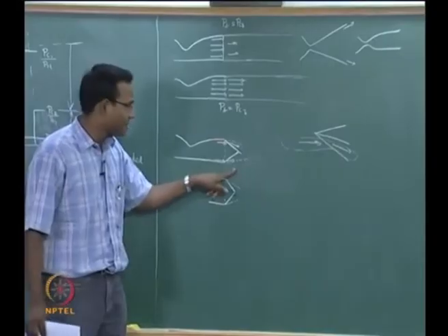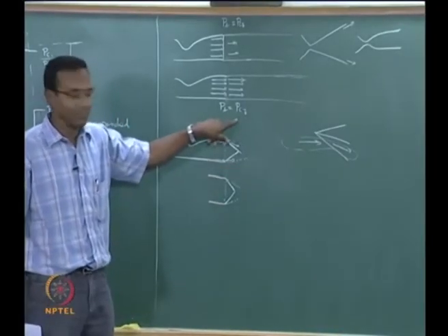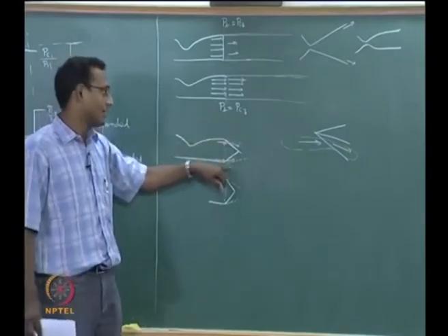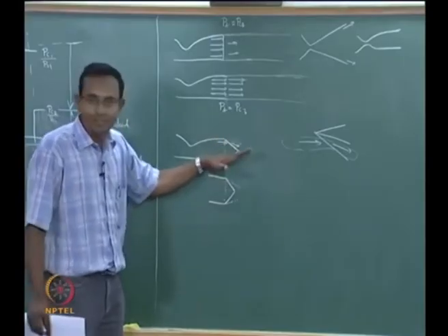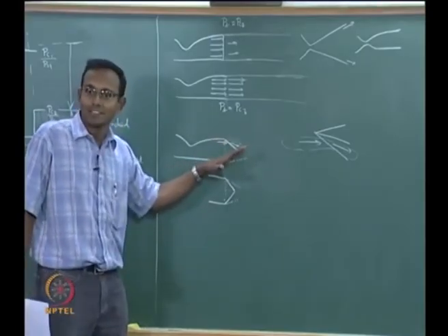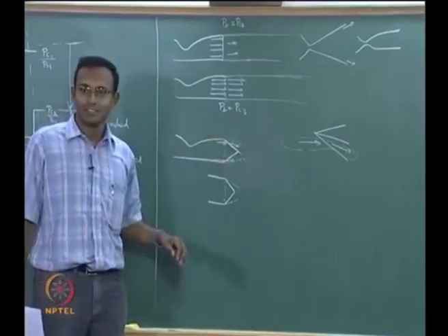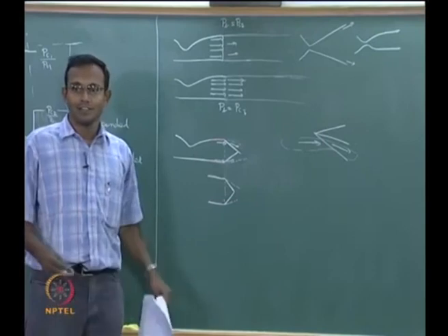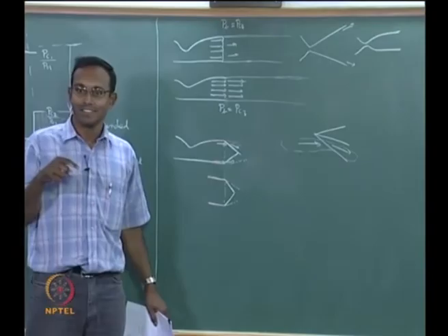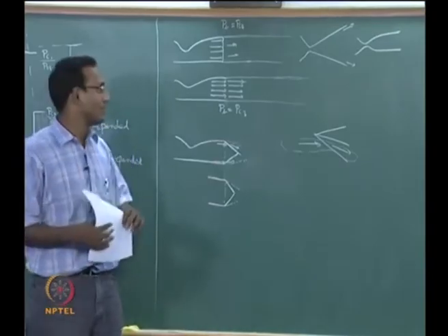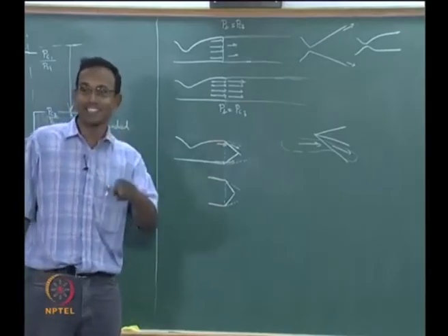I keep on decreasing my back pressure, it is going to tend to PC3 eventually. Back pressure is some value here, I decrease back pressure, what should happen here? My oblique shock should be less angle, beta will decrease, okay. When will it become this case? Do not talk about PB now, tell me something about the beta. Beta will not become 90 degrees, beta will not become 0, that is why I asked this question.